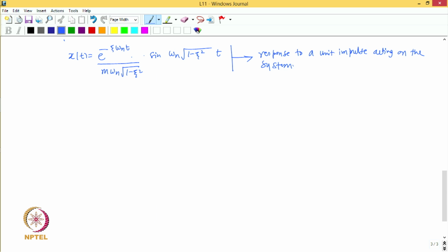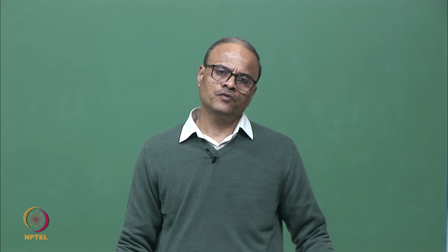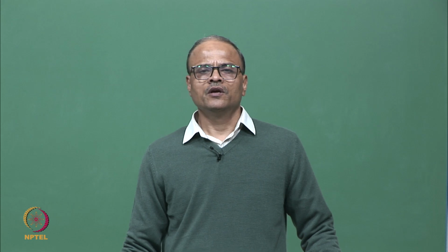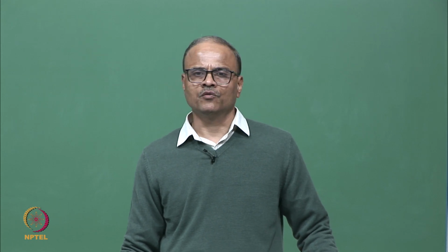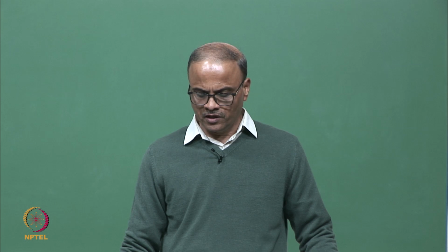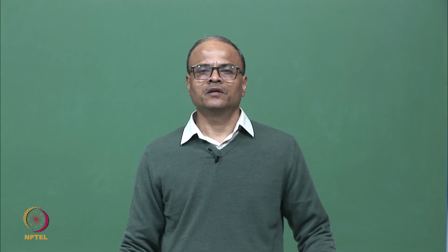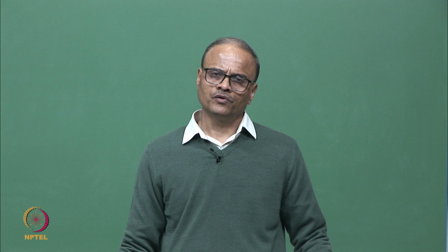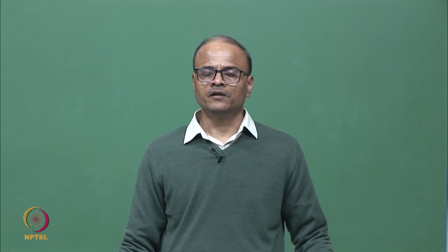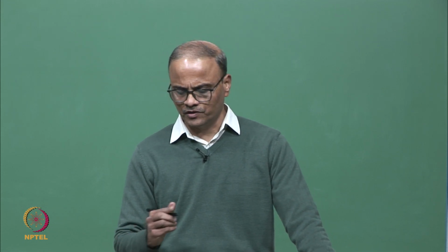And this is nothing but the impulse response function, IRF, because IRF is defined as the response of the system to a unit impulse. This is similar to the definition of the frequency response function. The frequency response function we defined as the response of the system to a unit amplitude harmonic force at frequency omega. Similarly, in the time domain we define the force as a unit impulse force, and the response of the system to this unit impulse force is nothing but the impulse response function.